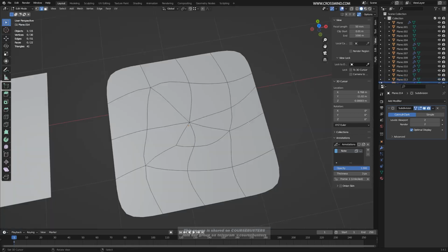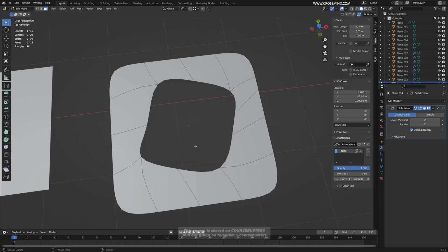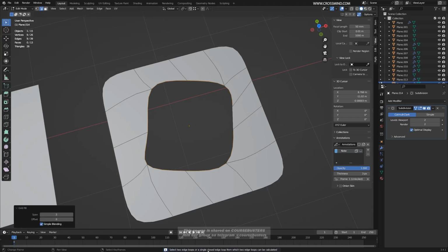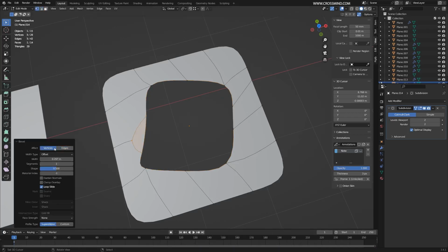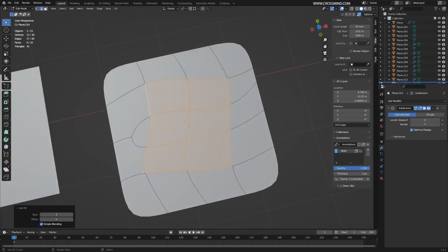Now there might also be scenarios where you can't really make sense of the mesh. There are just a few loops making no sense. So instead of fixing these, sometimes you can just use a simple grid fill. Just get rid of this face and then grid fill. If it says you need an even number of vertices, you can just bevel one of these vertices and then you have grid fill, which works for you. And then you can fix this one.